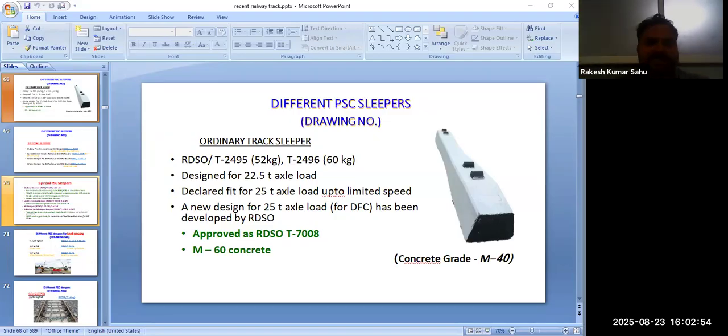So the advantages of wider sleeper as compared to normal sleeper are due to its increased rail seat area. Increased rail seat area results in a higher rubber pad below the rail. Its width and weight provide higher frame resistance against buckling, chances of reducing distress temperature with likely reduction in rail and weld failures.